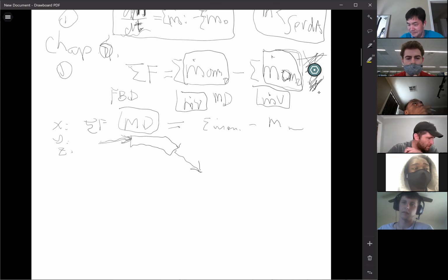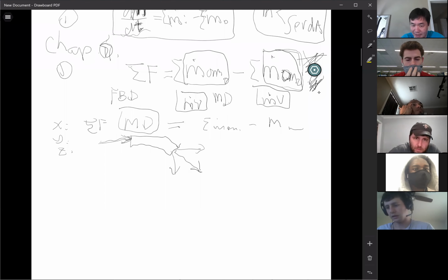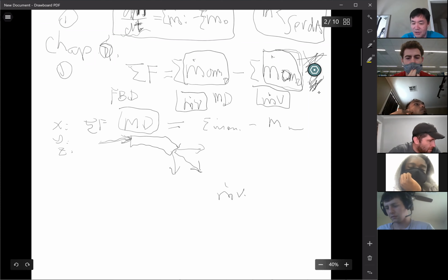You follow me? So for this momentum, that's the expression m dot v. This momentum has a direction. If you look at the x direction, this momentum is positive. If you look at the y direction, this momentum is negative. So when you calculate the mass flow rate times velocity, you already have the value. Don't use sign, just put the value there. After you calculate the value, put a sign in front of it.